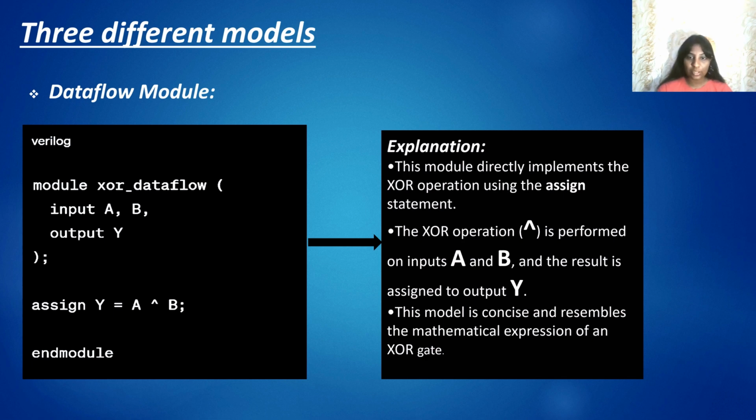This module directly implements the XOR operation using an assign statement. The XOR operation, which is the caret symbol, is performed on inputs A and B, and the result is assigned to the output Y. The model is concise and resembles the mathematical expression of an XOR gate.